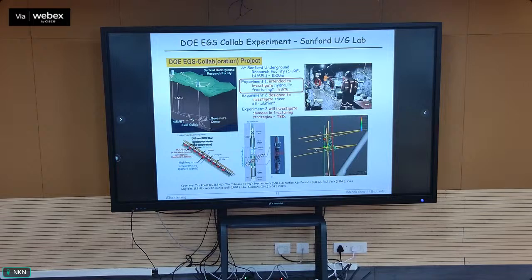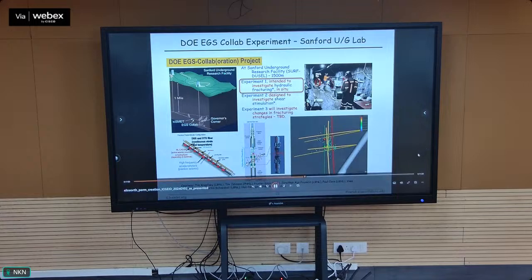So this well-instrumented experiment at 1,500 meters depth at relatively representative in situ stresses, where you're only a factor of maybe 10 meters away from the experiment, with the seismicity that you get from it being very well defined, and running this experiment in a variety of different modes. Running it in modes attempting to do hydraulic fracturing, attempting to do hydraulic shear, and to both measure the injection rates and pressure magnitudes, which give you some estimate of permeability, and also measure the ongoing seismicity as the stimulation proceeds.